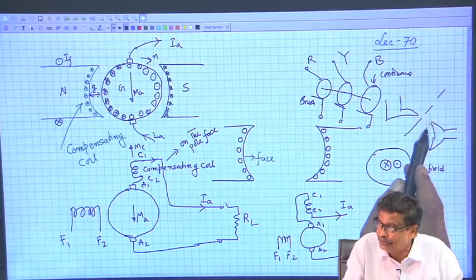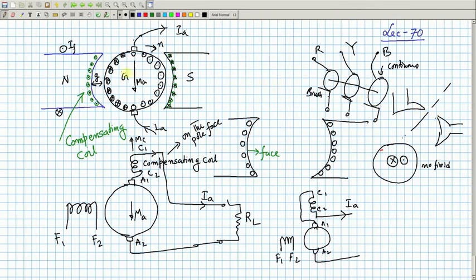So, in this zone, armature conductors are there, up to this point, but after that also cross dot is there. Can it fully compensate this? No. Most of the armature MMF will get nullified in this process, no doubt. But there will perhaps be some quadrature flux still, which will be reduced, no doubt, but may be present.